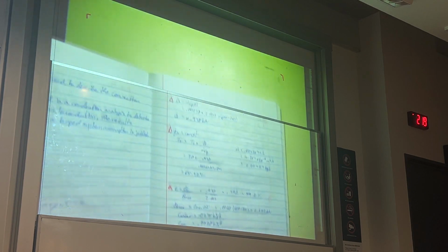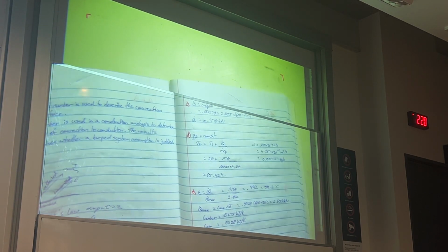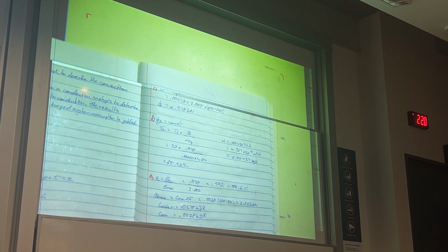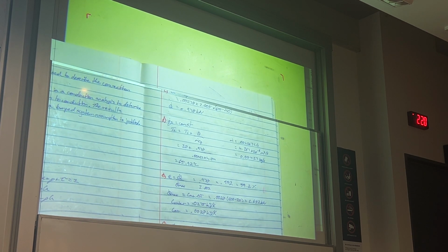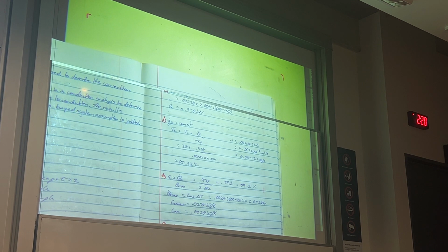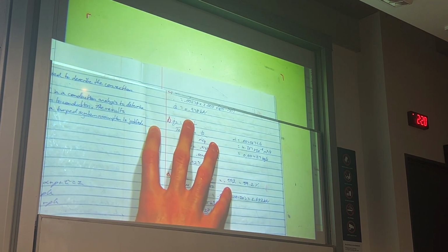The next part of this question is calculate the total rate at which the heat is to be removed by the heat exchanger. So we don't know the entrance and exit temps of the water, so we have to work off air. And it just comes down to a simple energy balance for the air.